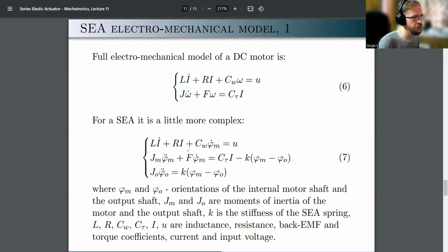That could be beneficial. Well, we can do the same here. For example, this can be made into a separate control loop where we would get desired I, right? This is what is typically done when we want the motor to act as a producer of torque, right? Because the torque would be produced here, right?